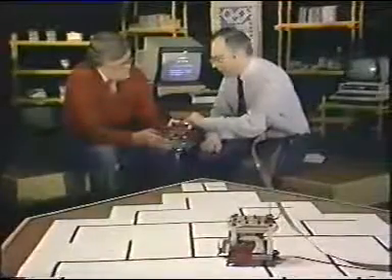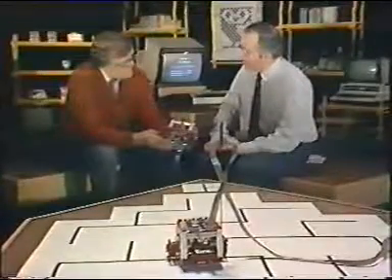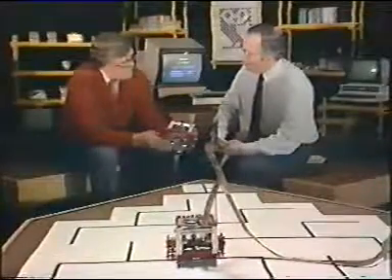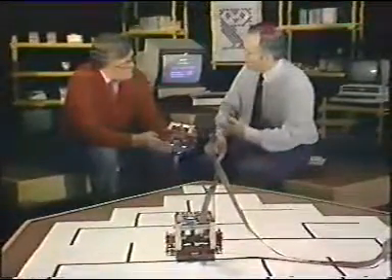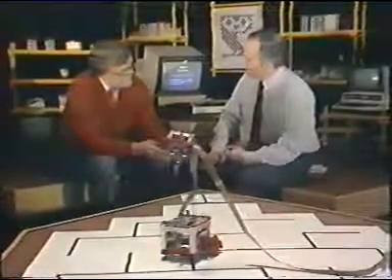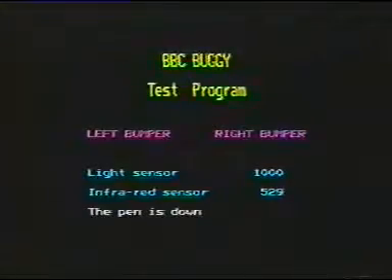This one's really rather different. This sensor emits infrared light on this side, which is reflected off a surface, and then the infrared is picked up here. So it can follow either a white line or a black line and determine which it's on. Now, it's actually an analog device, but the computer senses whether it is above a 50% level, whether it's above grey. If it's brighter than grey, it says that must be white. If it's darker, it must be black. Yes, you can see the two different values. When it's on black, they're 1,000, and down about 500 or so when it's on the white.